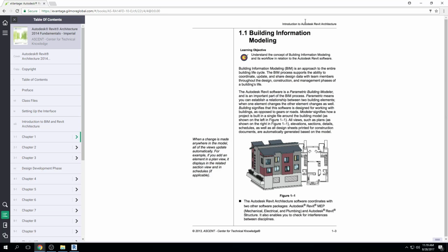In building information modeling, okay, the information portion is we input information into objects, right? So items that represent a wall also contain information in them that says this has gypsum on one side, it has a stud in the center, and it has gypsum on the other side, and a tile wainscot, okay? So there's information contained in our objects in this model, right? So good and bad, because right up front, we have to kind of define these elements, even if we don't know what they are, right?